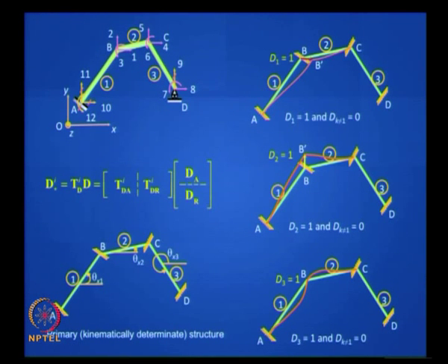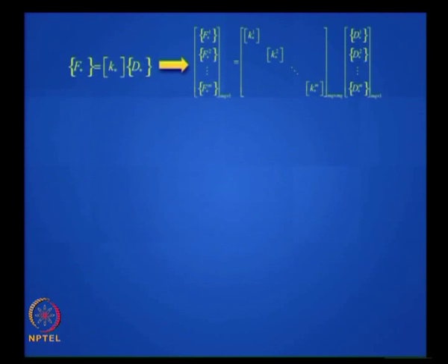You can actually do it from first principles using the physical approach, because we did a few examples earlier, right? But the computer has no feel for any physical approach; it has to do it mechanically, blindly, and that too is possible. Before that, let me talk of this matrix K star, which is sometimes referred to as the unassembled stiffness matrix.